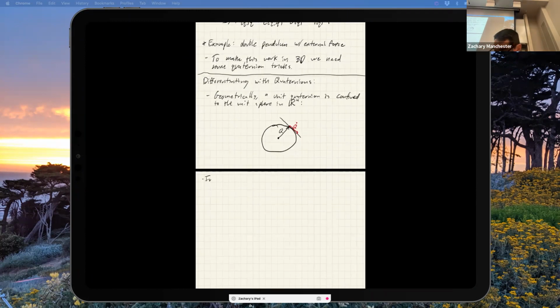So let's write that down. And this tangent plane is 3D. And this is the idea with omega. Omega is a 3D vector. So no matter what weirdo representation we use, that could be 3x3 matrices or 4D unit vectors, whatever, when I take a derivative, that derivative lives in this 3D tangent space. And I can always do some weird thing to map that back into some 3D omega vector. And in particular, for quaternions, we talked a lot about this, and it looks like the following thing,